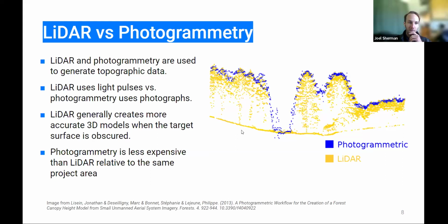All right, and another component here would be cost. Photogrammetry is much more common. The equipment required to perform the work and the workflows associated with it are moderately lighter, less expensive, and require less skill to capture photogrammetry data relative to LiDAR data. There are just more complexities in terms of how you're capturing that information. It's become easier in the most recent past with new systems coming out, but it still requires significantly more depth of knowledge to capture the imagery, capture the data, process it, and then deliver it as well. So that's the final note on those primary differences.